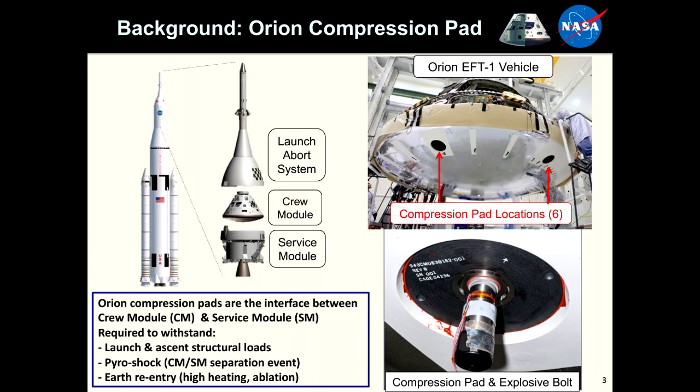So what we actually have here is a heat shield, which you normally want to be a low density material. You don't want to add much weight for launching into space. You have a heat shield that's low density, but in these regions where it's structurally connected to the rest of the rocket, you need a very robust structural ablative material system. And that's where 3D MAT came in, because we couldn't find a material to meet the requirements of that particular location.